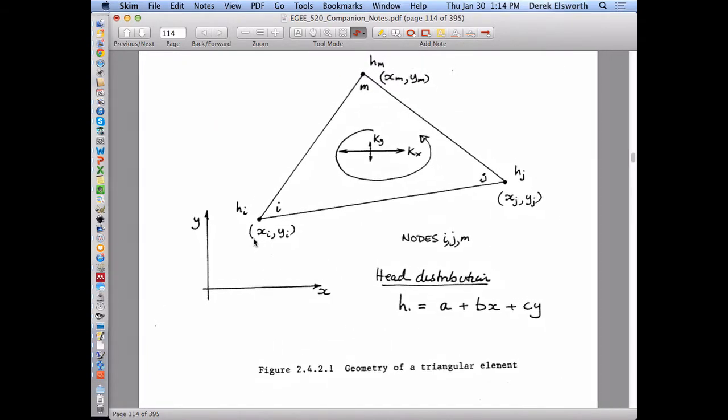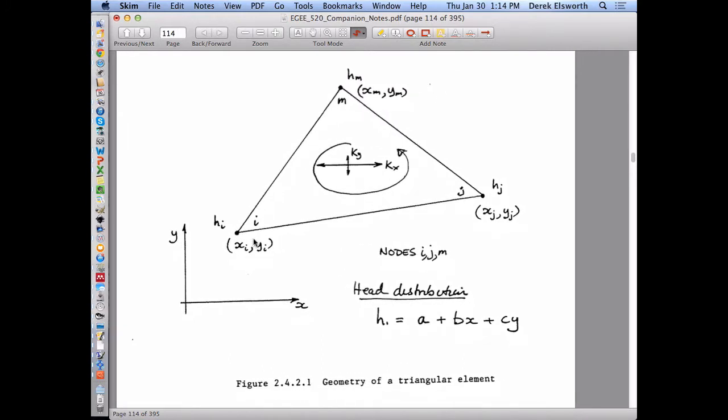So this is the idea. We're going from an element that had 2 nodes to one that has 3. It has a node at each end. We mentioned before that when we number these, they are just numbered sequentially I, J, and M. I guess K not because it's confusing with hydraulic conductivity. It can have hydraulic conductivities of different magnitudes in different directions. We won't actually do that in this case, but that certainly can be the case.